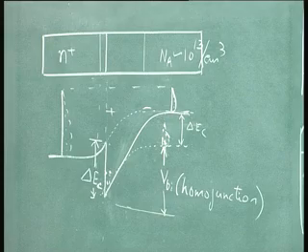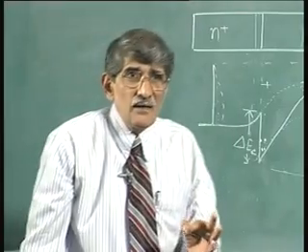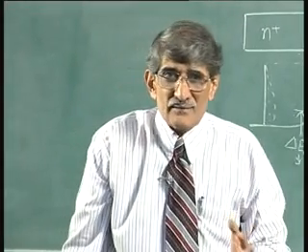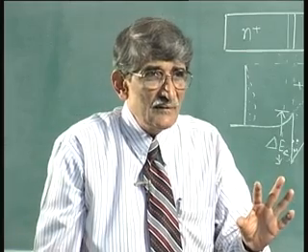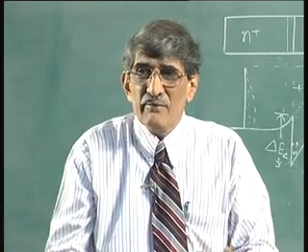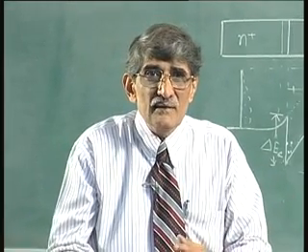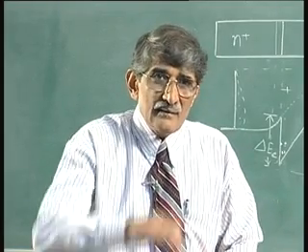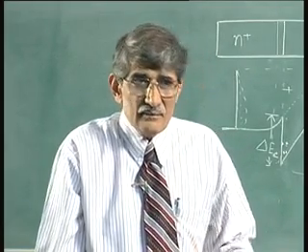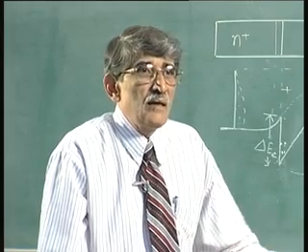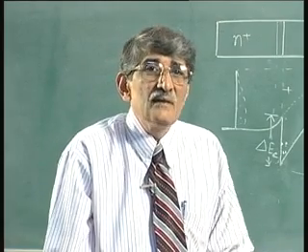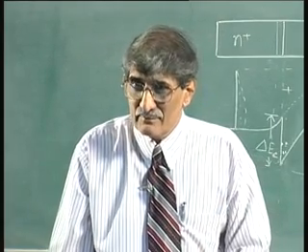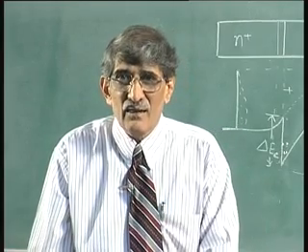If you reduce the potential, what happens to electron concentration? It reduces. So, the key thing is I can have control over the charge in that notch for a given device. I can control it by applying a bias to the junction. I forward bias that, the potential barrier reduces, that is the potential change in the gallium arsenide reduces, and electron concentration reduces. Okay, we will recall this concept later on.